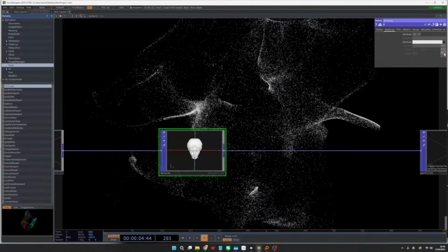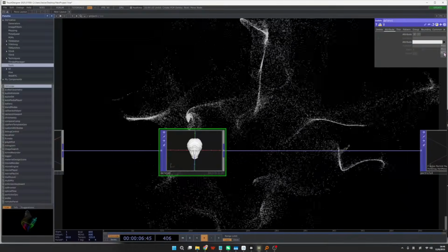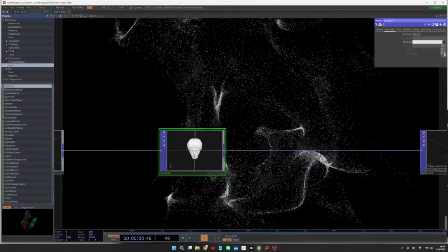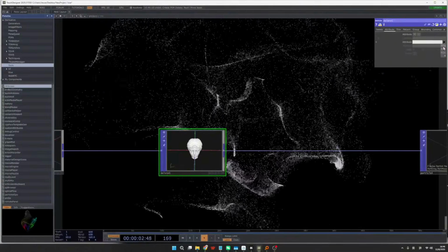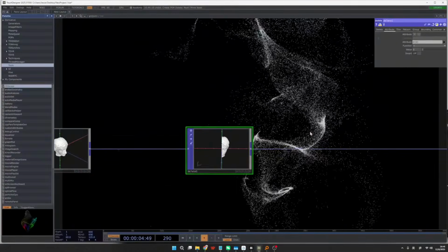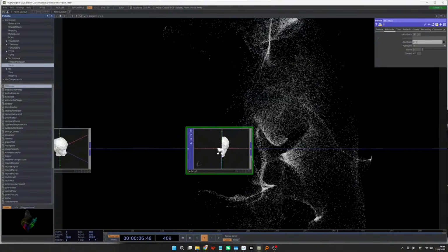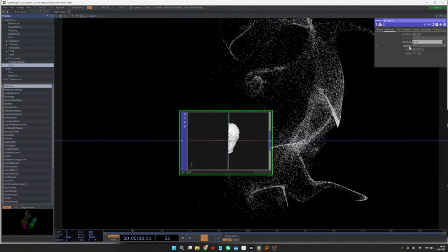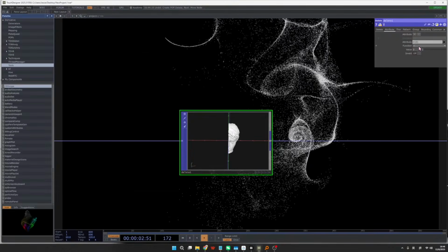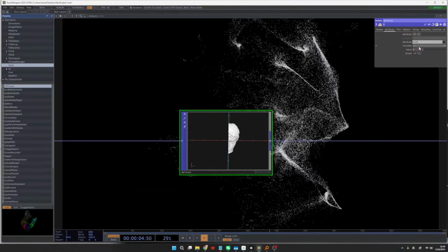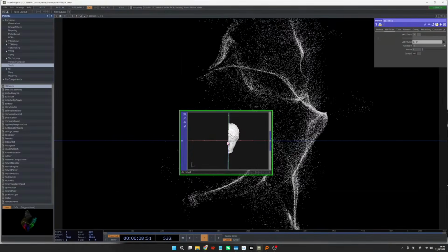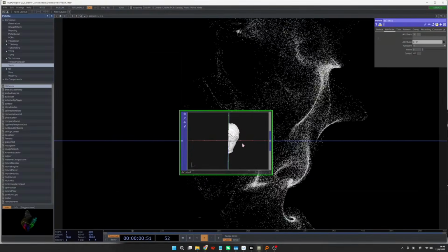So here I want to cut it vertically, so I'll cut it based on its X position. So I choose P0. You see, the second I choose it, it's already cut in half, because in here it has a function. That means any values that go below 0 on the X axis will be cut off.